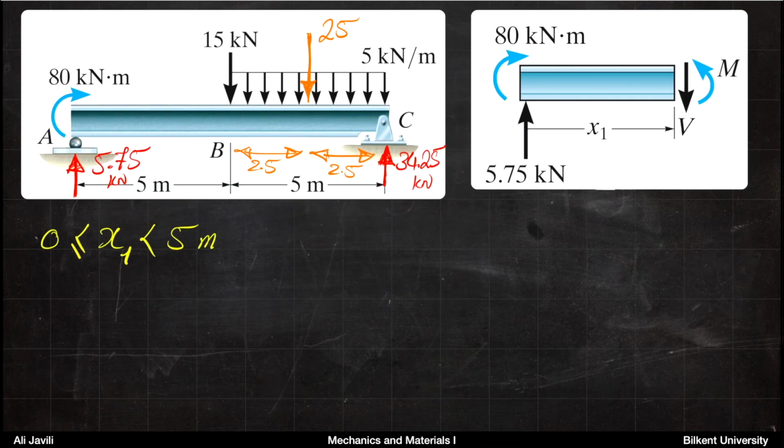Okay, now that you have the reactions, you have everything for the beam to proceed and to calculate the internal forces or internal loadings, in this case, a shear force and moment. So you cut the beam at a point here, between A and B, and then you can calculate V and M for this portion, but then for the portion from B to C, we cut it separately.